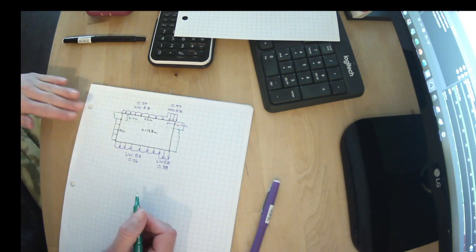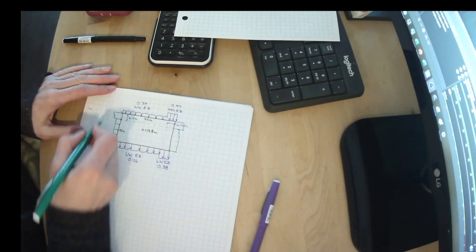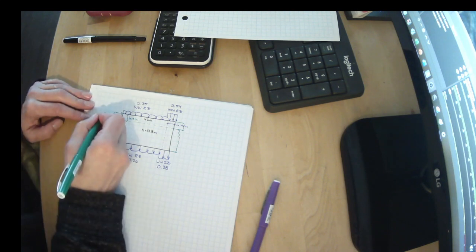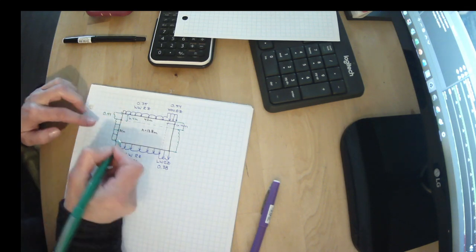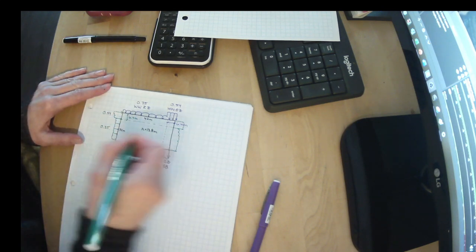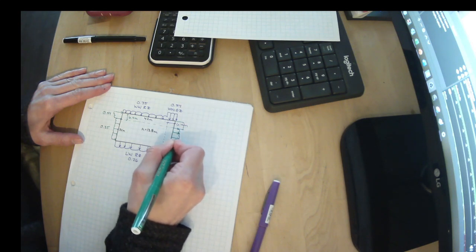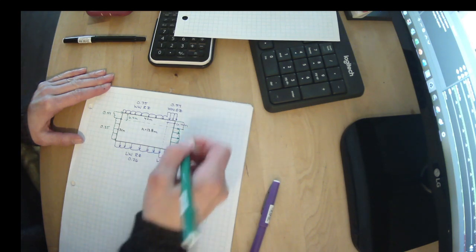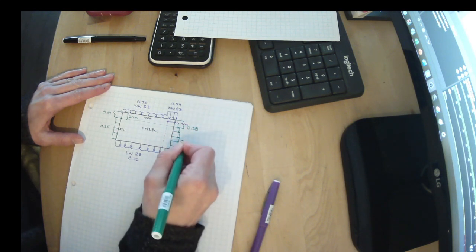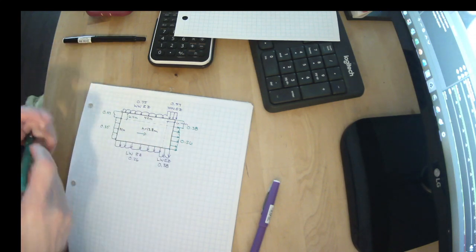So we have to do the same thing going in the other direction, where we have our end zone windward, or 0.54, and we have our windward regular zone of 0.35, and all of these arrows go in this direction. So this is 0.38, and this is 0.26. And we want to figure out the total load on this building for each of these directions.